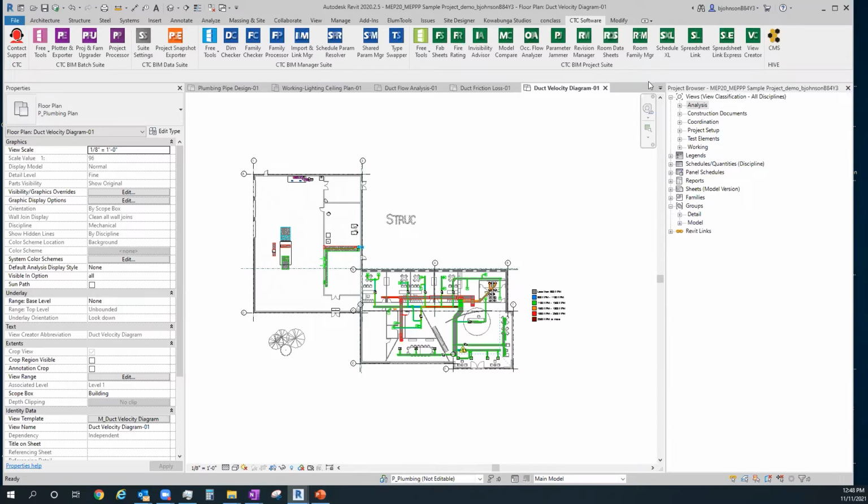So other things in our project suite, Schedule Excel would let you take an Excel schedule, bring it in as a schedule inside of Revit, place it on a sheet. So things that are not driven by parameters, I like to be able to bring in Excel spreadsheets and actually plot them, not have to do images or OLE type things or a pass through into CAD so that the CAD can have a CAD link into Revit and I print off of that. Don't want to do any of that stuff. I just want to pass it directly from Excel into Revit.